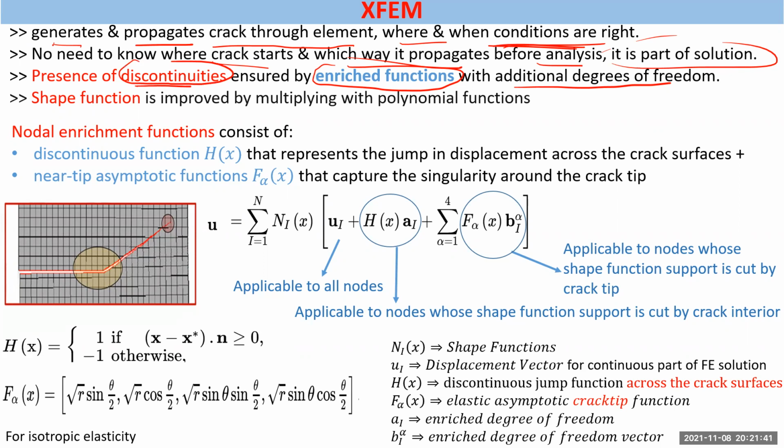How do we associate these phantom nodes in our displacement equation? Displacement is the one having the discontinuity, right? If you remember, u equals sigma Ni Ui, that is N1 U1 plus N2 U2 plus so on. So what are these N's? U1, U2, U3 are nodal displacements. Does anyone remember this equation, u equals sigma Ni Ui?